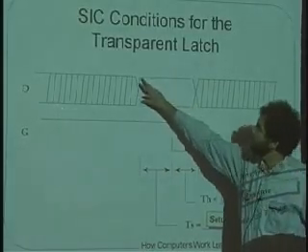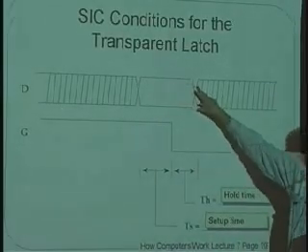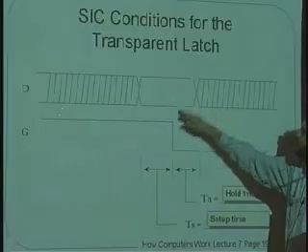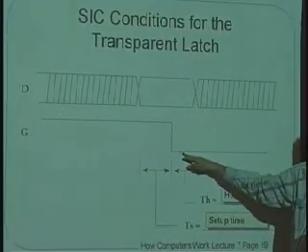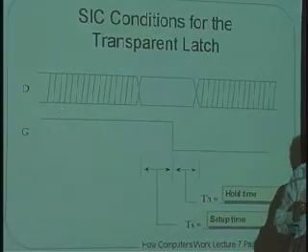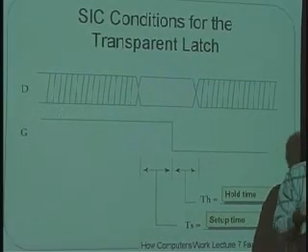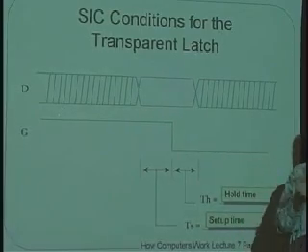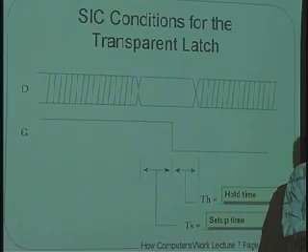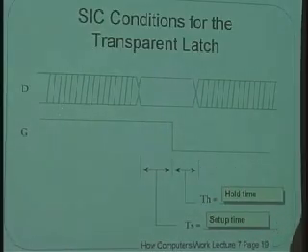And so we'll establish the setup time beforehand and the hold time after and say that this guarantees that only one input has changed at a time on that circuit, and thus the circuit is hazard-free, and thus it will be able to hold on to the value properly. And there will be no glitches going around and around the loop, but rather just a constant value going around and around the loop. And so this is how we're going to build this latch.